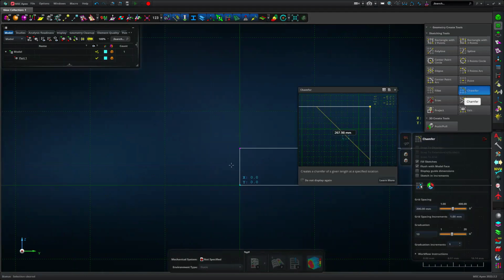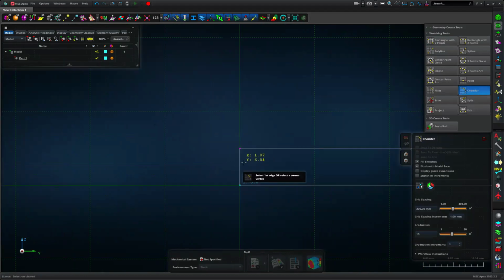Okay. Just click the two edges using your left mouse button. You can click one vertical and that horizontal line, and just drag a little bit. You'll be able to see the chamfer there actually. So let's give some 8 mm to that chamfer. So it will basically create a groove kind of thing. 8 mm.